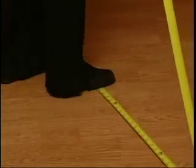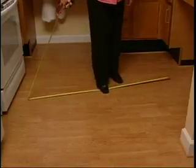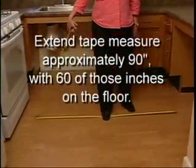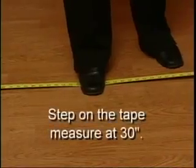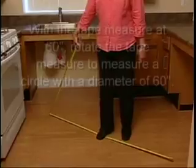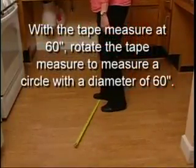The survey team will now measure the unobstructed turning space in the kitchen using a tape measure. To calculate the unobstructed turning space using a tape measure, extend the tape measure to approximately 90 inches, with 60 of those inches on the floor. Step on the tape measure at 30 inches. While keeping the tape measure at 60 inches, rotate the tape measure with your foot to measure a circle with a diameter of 60 inches.